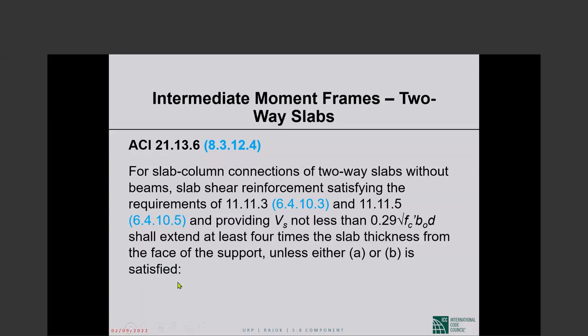This is the prescribed amount. Reinforcement capable of developing a shear of 3.5 square root of f sub c prime. But in reality, it is not at every joint. We said at joint. So I'll give you more details. But this is in principle the origin of the requirement.